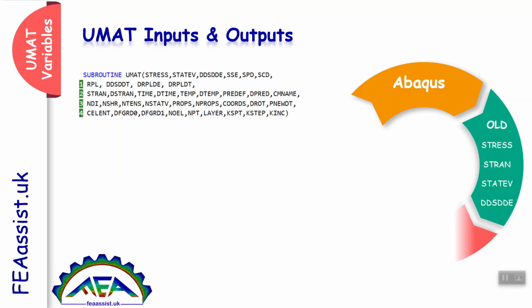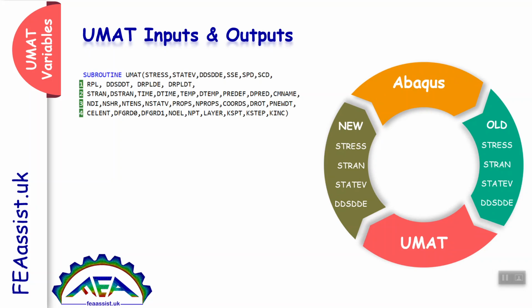transferred to the UMAT. In the UMAT, we need to write some equations based on our constitutive behavior to recompute all the variables, and return all these variables back to Abaqus. This is how Abaqus and UMAT interact with each other, which is necessary to write a well-working UMAT.